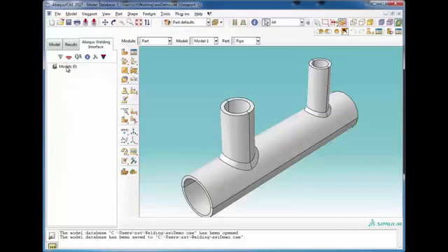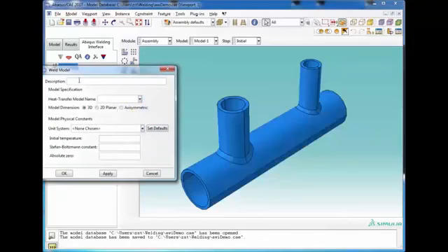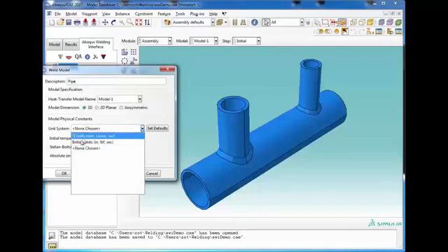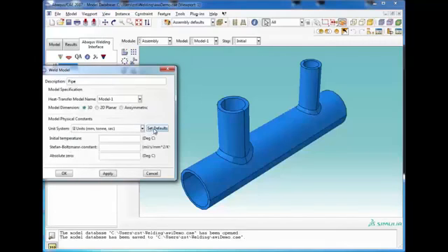Once all that's done, we get to the point where we're ready to work on the Abaqus Welding Interface. The first thing we do here is right-click and say Create, which doesn't necessarily create a model, but just initializes some things that we're going to need in the model. When we're working in the AWI, we typically are going to be working on the heat transfer model, and at the very end of the process, the AWI will automatically generate a stress model. So the sequence is a sequentially coupled analysis: it does the heat transfer first, followed by the stress model. In this case, we just have the one model. We're doing 3D. We're going to use the default unit system of SI units, and we'll set some default initial temperatures, Stefan-Boltzmann, absolute zero.